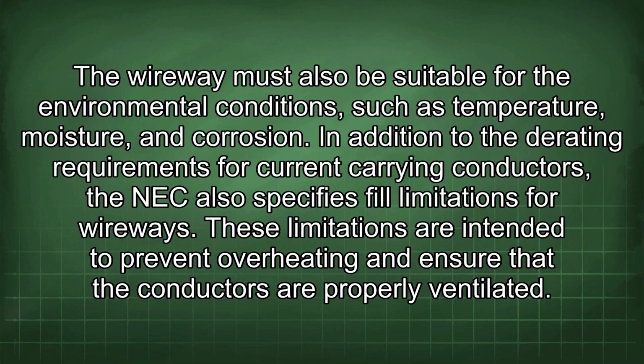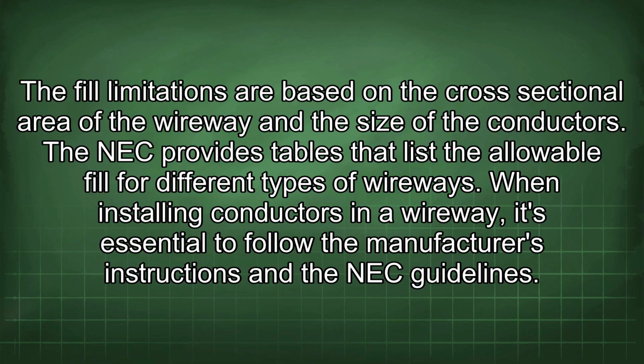In addition to the derating requirements for current-carrying conductors, the NEC also specifies fill limitations for wireways. These limitations are intended to prevent overheating and ensure that the conductors are properly ventilated. The fill limitations are based on the cross-sectional area of the wireway and the size of the conductors. The NEC provides tables that list the allowable fill for different types of wireways.